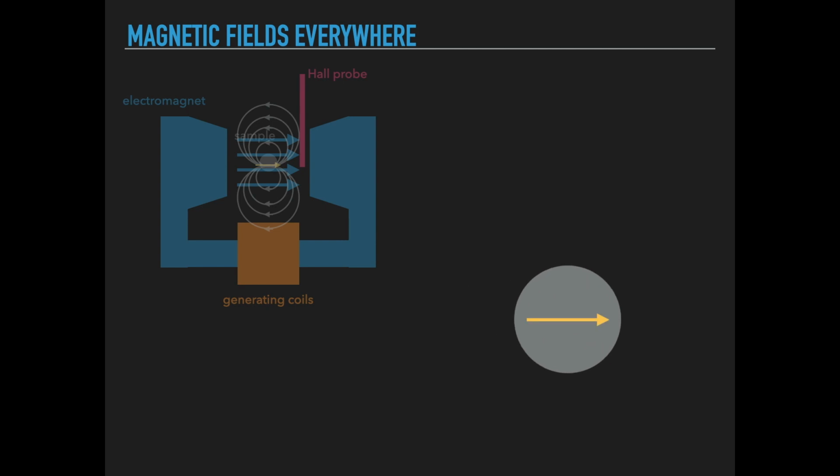Let's now have a closer look of what happens in the sample. When the sample is magnetized, at its surface appear magnetic poles that we conventionally call north and south. These poles are the sources of the fringing fields that we discussed earlier, but also they are responsible for a different field that again goes from the North Pole to the South Pole as any field that is located inside the material, inside the sample. This field is anti-parallel to the magnetization. Since it is located inside the sample, and because of its direction that opposes the magnetization, this field is called demagnetizing field.